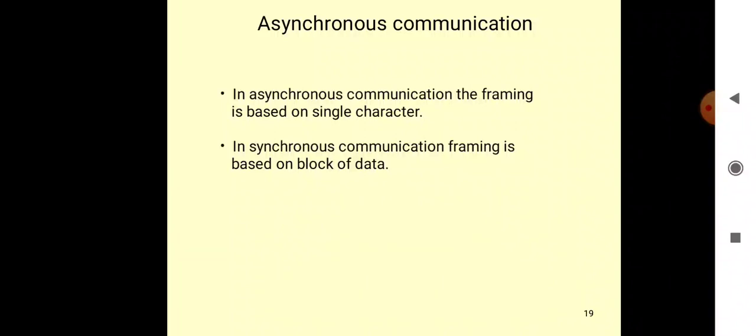Clock recovery: an asynchronous digital system can function with a receiver clock whose speed is only approximately the same as the transmitter clock, because the clock is reset at the start of each character, using simple crystal oscillators at each end running at the same nominal frequency. However, the longer message block used in synchronous communication makes it necessary to lock the two clocks together exactly. Otherwise, the receiver clock would soon begin to sample the signals at the wrong time. So a clock recovery circuit should be maintained in synchronous communication.